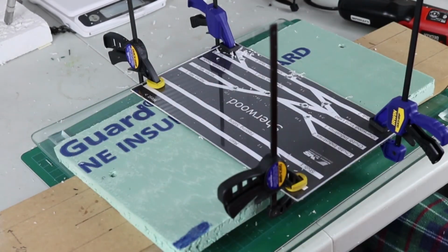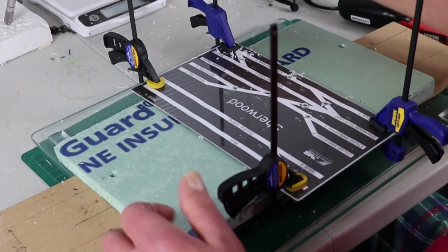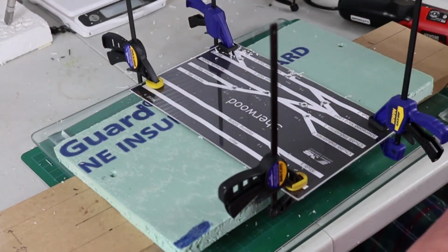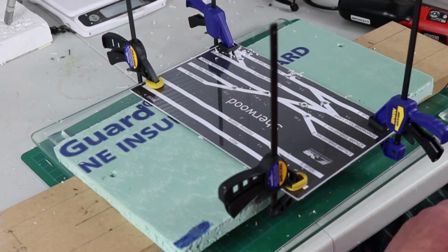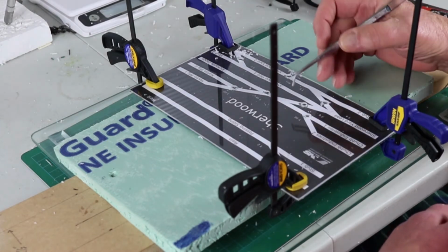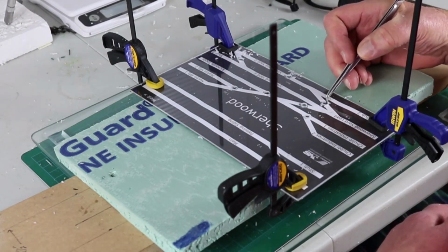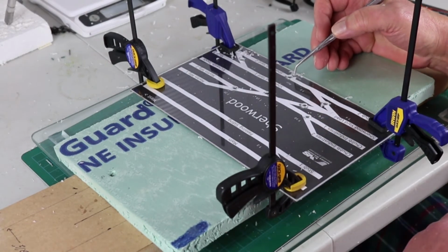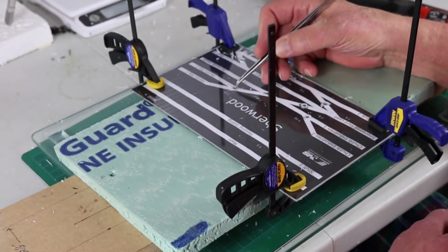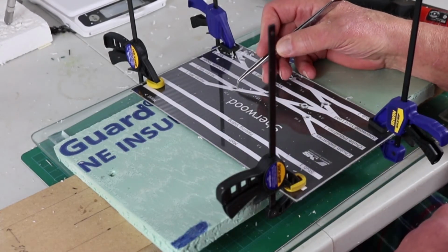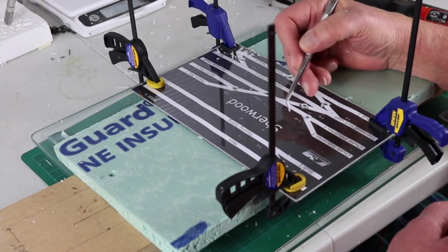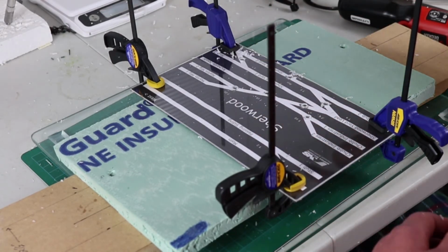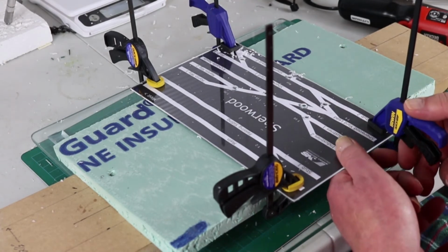There we go. All the holes are drilled. Now, we're going to take this apart. And you can see we've created quite a mess here. Sometimes the paper gets damaged when you drill the hole, and sometimes it doesn't. So if that occurs, and it's bad enough that the nut that's around the toggle switch won't cover it, all you do is print yourself out another diagram and cut the holes in there manually using a hobby knife with a sharp blade.